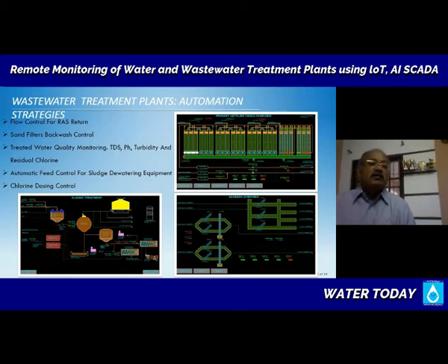Now, all of the functions that we have talked about can be done with a SCADA or PLC, programmable logic controller type concept, where the devices, the PLCs, can remain in the area. So you keep the wiring to a minimum, keep the controlling device very nearby, and then you network them all and connect them with the central computer system server in the control room, so that you can sit there and monitor and manage everything. And you can minimize the cost of cabling for monitoring and automation purposes. So your plant can have multiple PLCs sitting here and there, all integrated into a central monitoring platform.